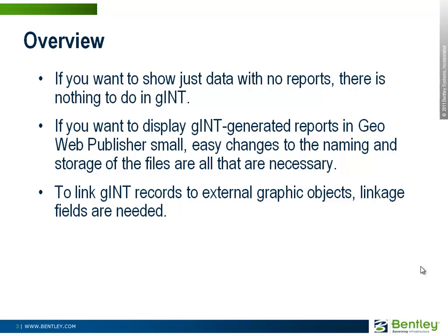Now, if you want to link gINT records to external graphic objects, linkage fields would be necessary in your database. And the section lines that we saw with the letters along the side, those were actually stored in MicroStation. And we needed a link field within the gINT database that ties each alignment, which is what those lines are.